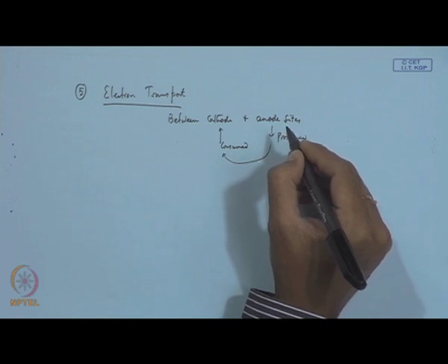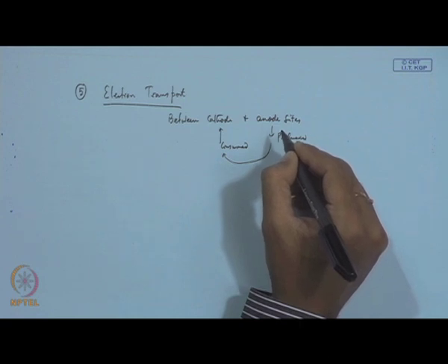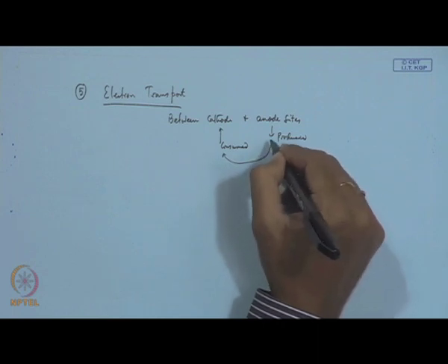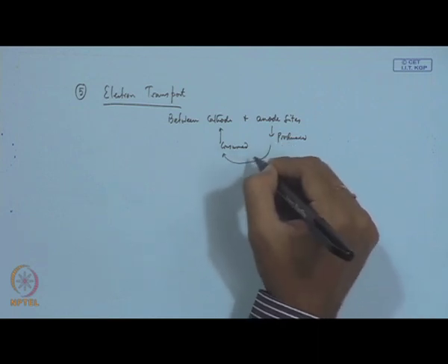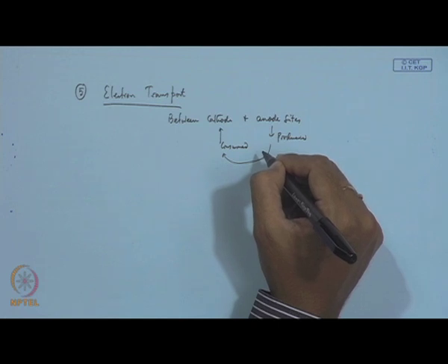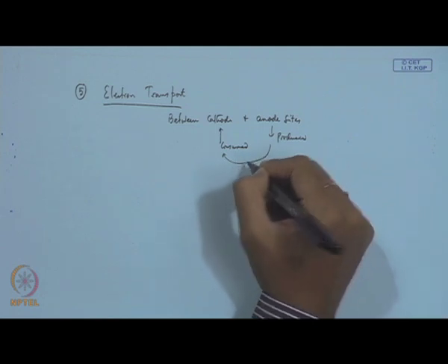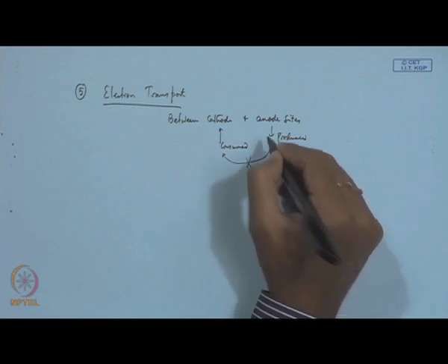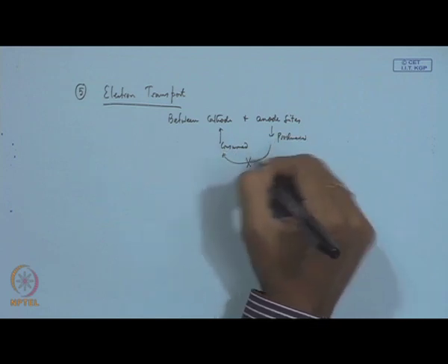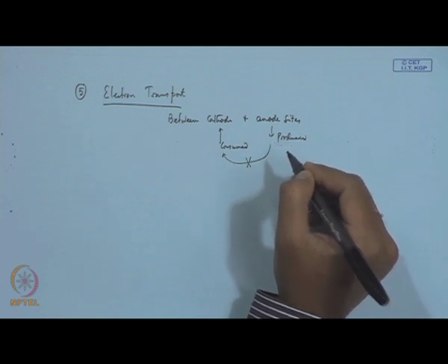Okay. So without flow of electrons between anode and cathode, these half cell reactions will not be completed. So that means there must be some means like an electrical wire connection, I mean electrons flowing along a wire from anode to cathode could be a way. So if by some means we can hinder this electron flow from one side to the other, then possibly we can reduce the extent of corrosion.